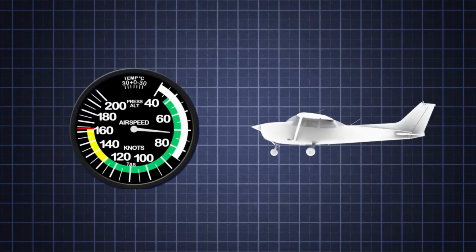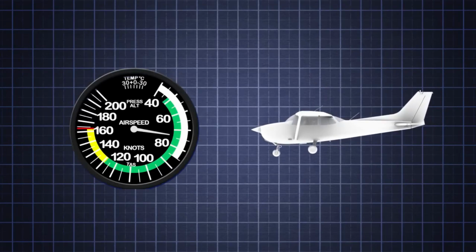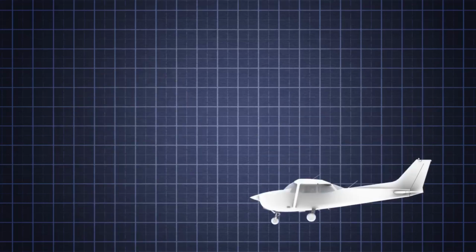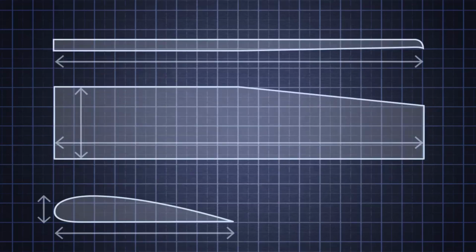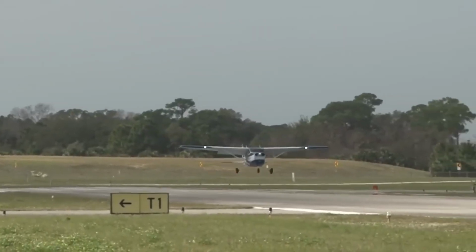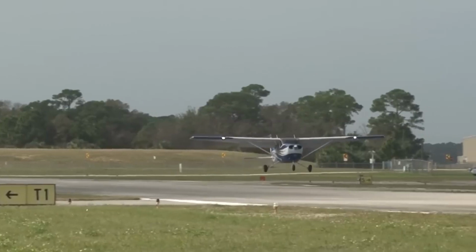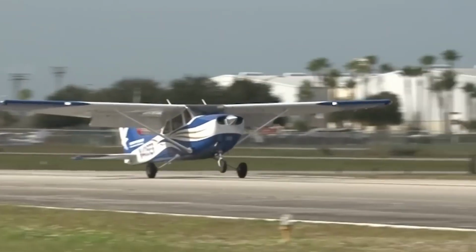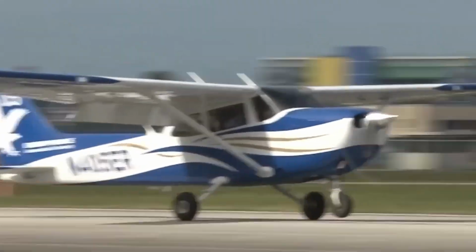Newer aircraft are generally made with consideration to this by fairing parts along the fuselage, teardrop, so that turbulence and form drag is reduced. Total lift must overcome the total weight of the aircraft, which is comprised of the actual weight and the tail-down force used to control the aircraft's pitch attitude. Thrust must overcome total drag in order to provide forward speed with which to produce lift. Understanding the aircraft's relationship between these elements and the environment provides proper interpretation of the aircraft's instruments.